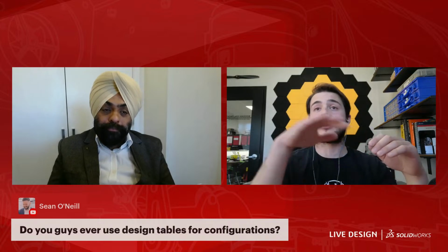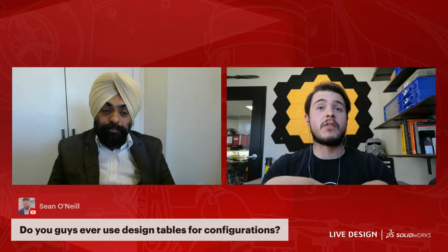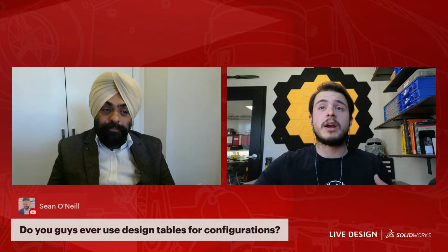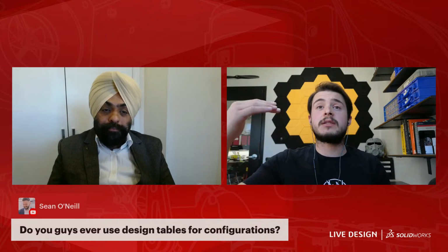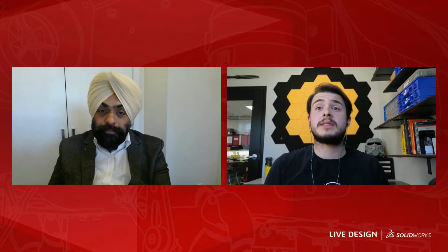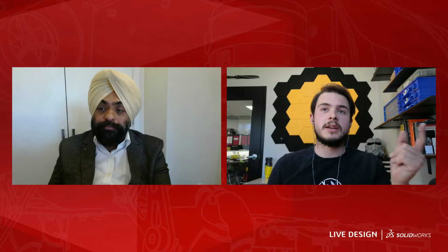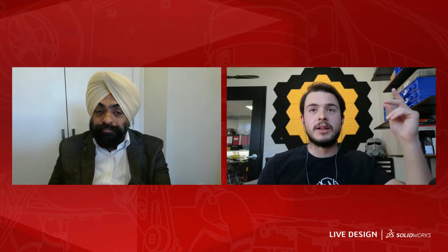And then we're basically able just to populate this based on the spec sheet of every one of these cylinders and create a giant array and a full library of every hydraulic cylinder that we have on the power loader, all in one single assembly. And that makes it super, super easy to basically say, like, oh, I need a different size cylinder, get the specifications, import into the design table, and now we have a full model with all the new dimensions.